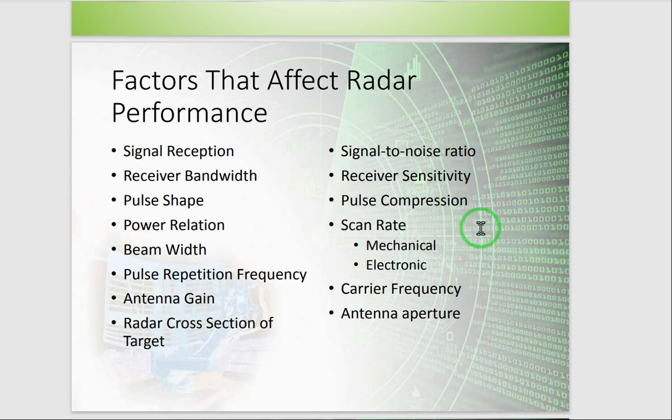Then the scan rate: definitely if the switch, or the duplexer that is used as a switch, is not working in the range or is scanning or switching more, then there is definitely a performance problem for the radar, because as the switch goes through the transmission and the reception, if it doesn't end it, there will be an error and it can also damage the radar.